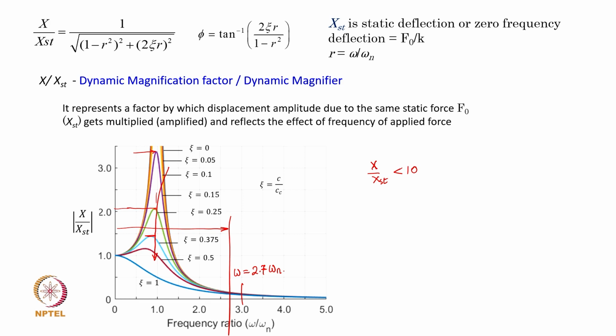But at the same time, as we shall see in more detail later in this particular topic of forced vibration, arbitrary increase in the damping value can become counterproductive, right. So, we must not use damping as much as we want, but it should be very carefully calibrated and chosen to the bare minimum. I mean bare minimum in the sense you can go for a larger damping, but just enough to take care of these resonant amplitudes, because later on you will realize lesser the damping better it is.